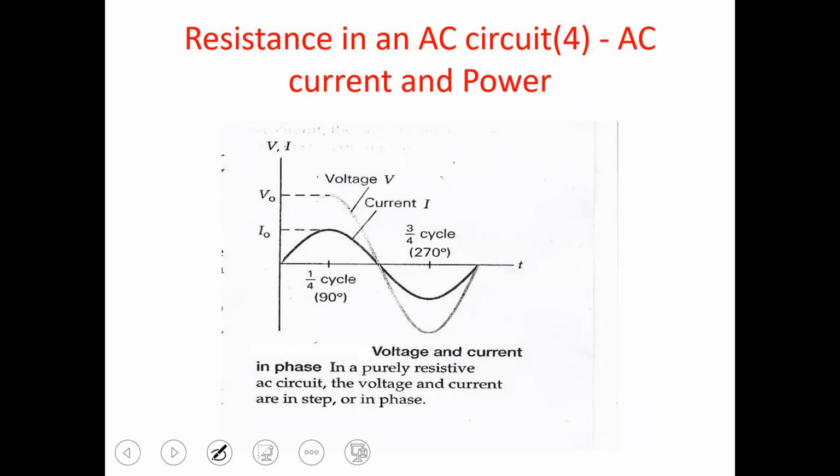At least the transformer has two coils, the primary coil and the secondary coil. When you put voltage in the primary coil of the transformer, you get an output voltage, right? The voltage you put in must be an alternating voltage.